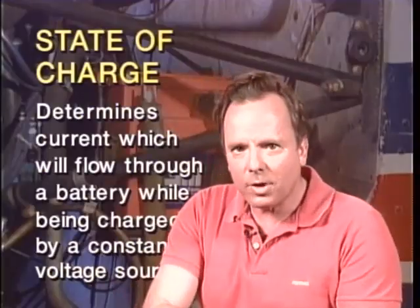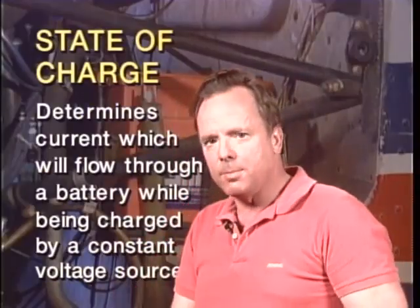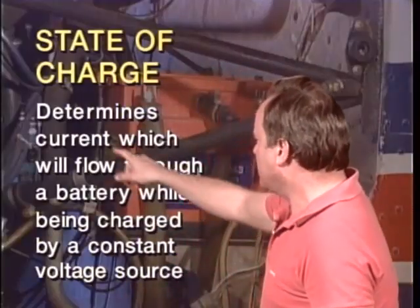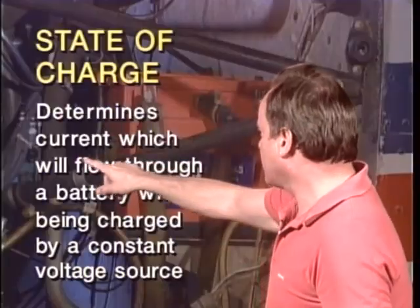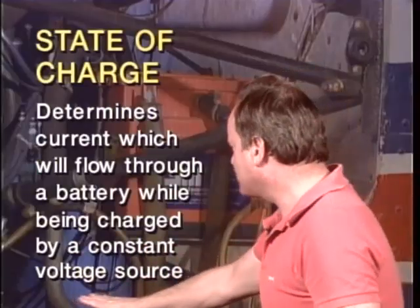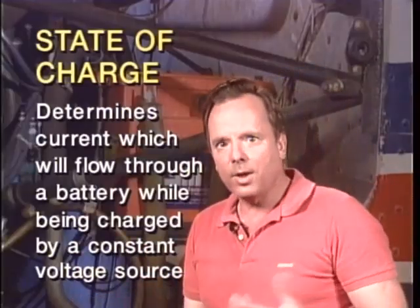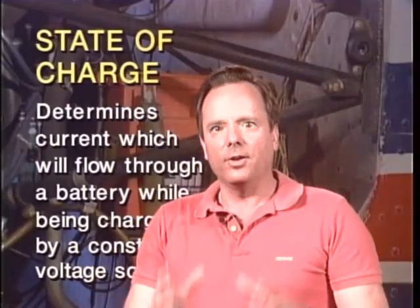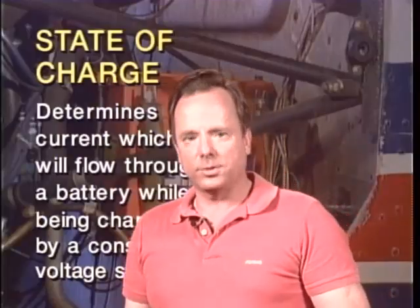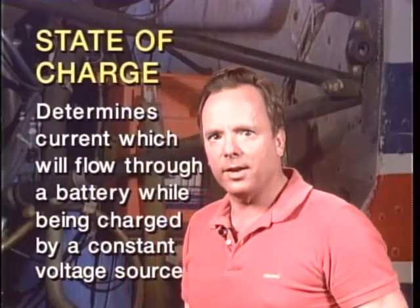And when the battery is extremely low, a lot of current flows into the battery. But when it's charged, very little current flows into the battery. So it's the state of charge that determines the current which will flow through a battery while being charged by a constant voltage source. By the way, the other way you could charge a battery, and you do this very often on certain batteries, is a constant current source. We'll talk more about that later on.